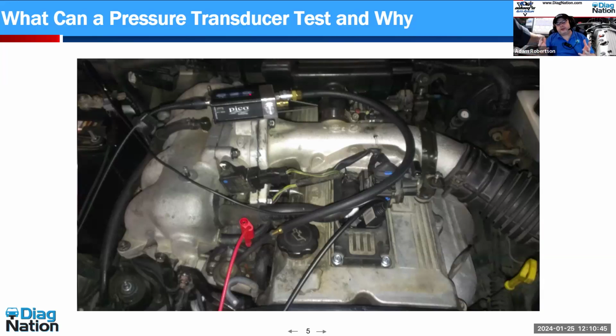And the answer is that although every one of my injectors may go click, click, click, I may hear them click. Does a clicking injector verify that it dropped hydraulic pressure? Does it verify that when it opened, that fuel came out? And the answer is no, Adam. They can click and nothing can come out.